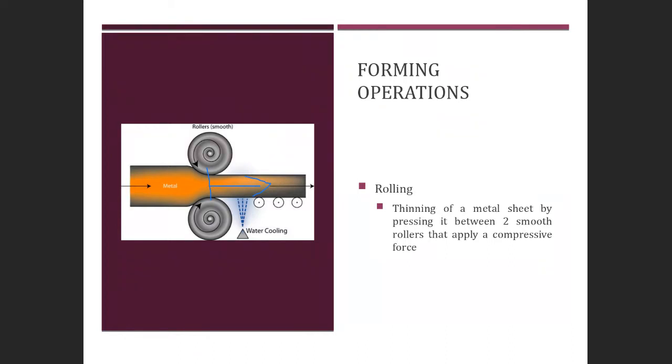If you were looking at producing then an equiaxed grain structure to relieve, for one, the residual stresses that have been implemented by your cold form process, then that means this piece will then go into an annealing process. So it's a completely separate process that occurs at a different location than the rolling mill per se.